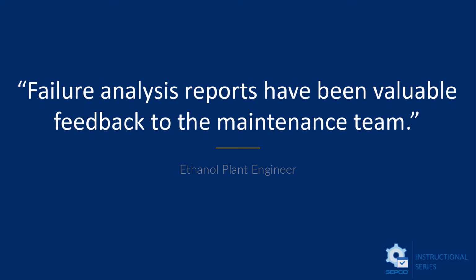Pipe support has been another one that we found a lot lately. These products with the discharge going straight up 10, 15, 20 feet in the air with decent sized pipes on there that are full of product is very heavy, pushing down on that casing or on that volute.